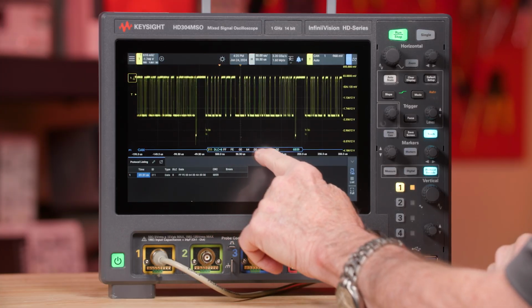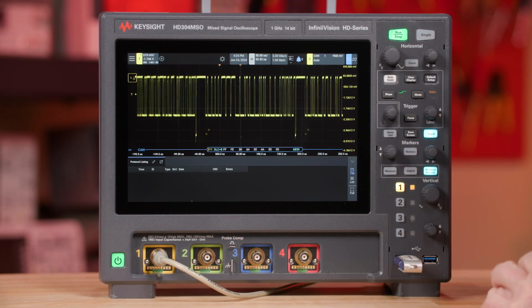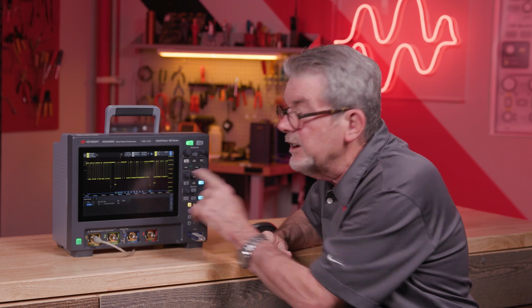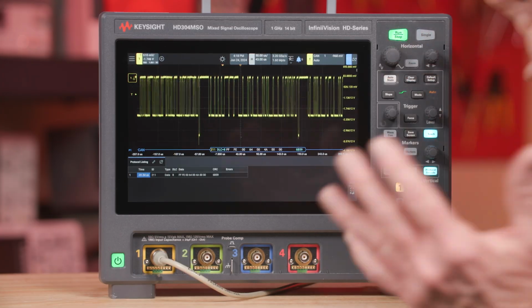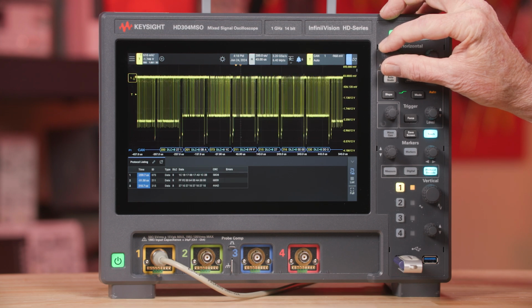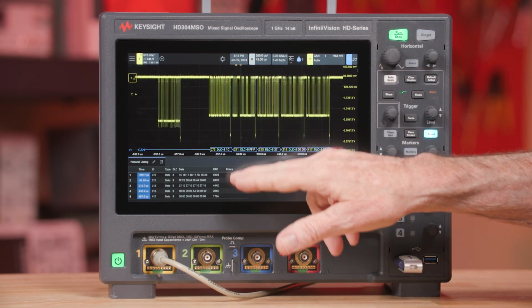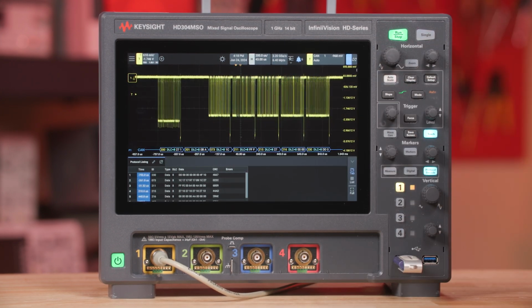And here you see the 8 data bytes followed by the CRC, currently color-coded in blue. That means it's correct. Now if it was red, had red font, that would indicate a CRC error. Now if I scrunch more frames on screen by changing the time base, we can see more frames down in the protocol lister. So now it's decoding symbolically with the DBC file.